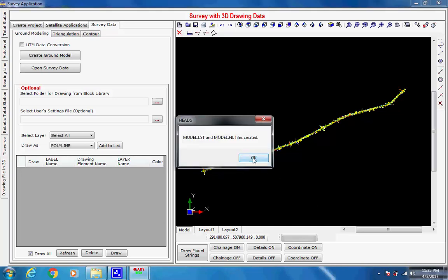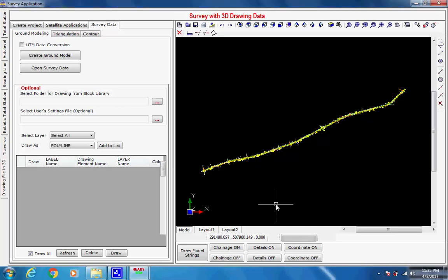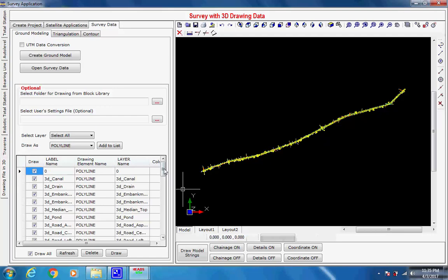The data in the total station survey data file must be made available in the following format and saved as a text file, for example survey.txt, which can be opened in Notepad. It has 5 columns of data. When a data record with serial no. 0 is met, as after serial number 5, then it discontinues the last feature and reads a new feature, from serial number 1, in the ground model.